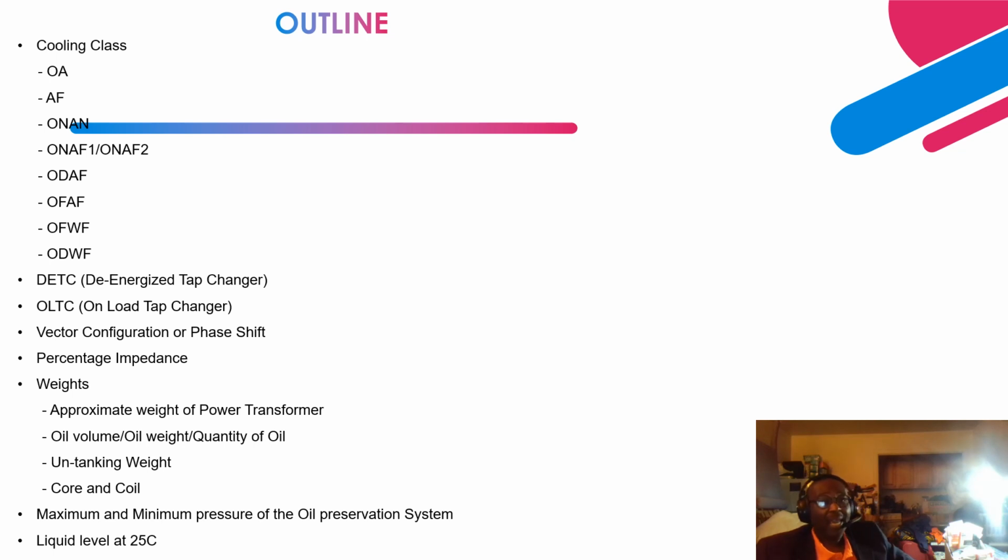The 1 is the phase shift between the high voltage side and the low voltage side. It means that the high voltage side is leading the low voltage side by 30 degrees. 1 means 30 degrees based on the clock system: between 12 o'clock and 1 o'clock, there is a 30 degree angle.